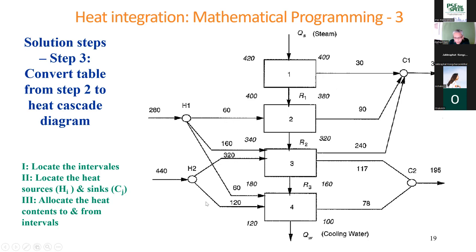and now is the nice part. How do we get the equations? It's very simple. For every interval, like I'm showing for interval 2, around the interval, whatever is coming in and going out, we have to do the energy balance. So what we see here is R1 is coming in, R2 is going out, 60 is coming in, 90 is going out. So we can make the equation for this, and similarly we can write the equation for this, this, and this. What will the equations look like?